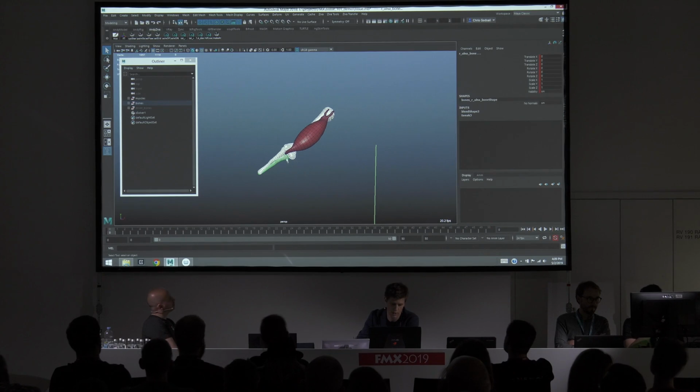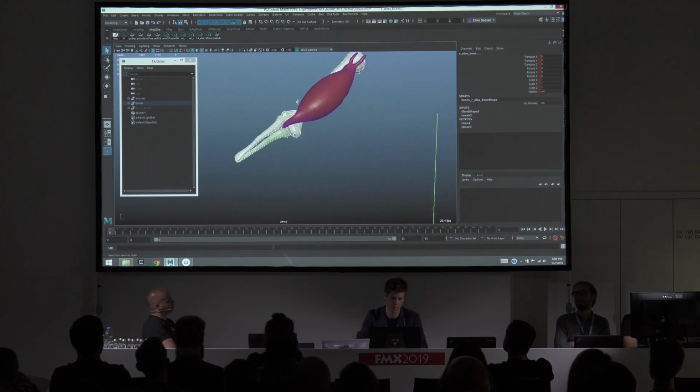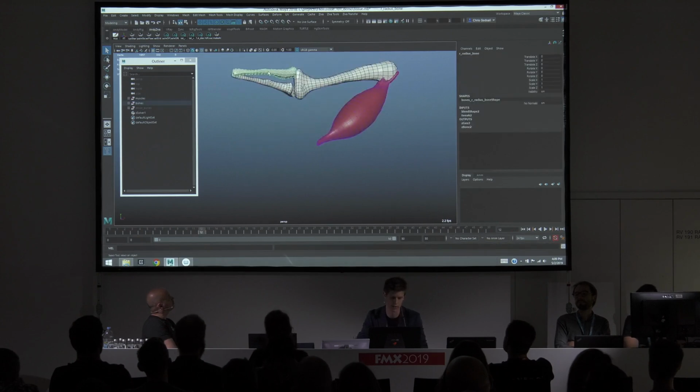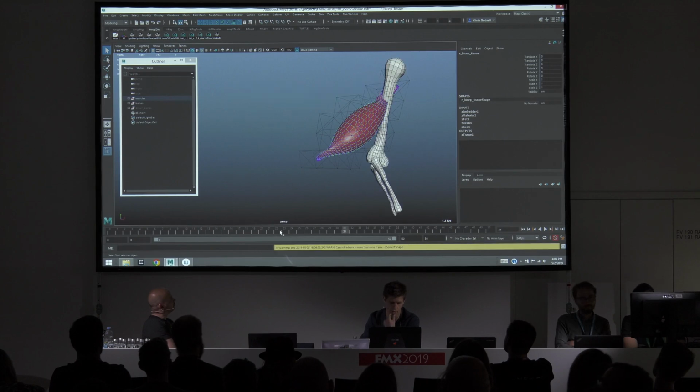So these objects here, I'm going to convert to Ziva bone objects. Under the Ziva menu, I can come down to add simulation component bone, and you'll see that we got some draw stuff here. When I move this around, you're going to see these things follow along. You'll notice that the tissue didn't update because it's a physical solve. It's dependent on the frame before, so you can't jump randomly in the timeline.